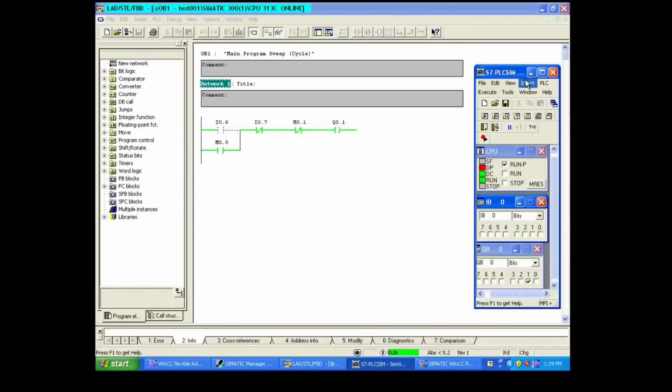No. How it is means, go to view or go to insert and bit memory. Yeah, in bit memory it is a memory. Can you see? M0.0 is on. So whatever bit you have turned on in SCADA is communicated to the PLC's M0.0. Okay, because of this fellow turned on, the same address I have used in a program, so it is also on. Got it? Can you get the point how it is getting interlinked?